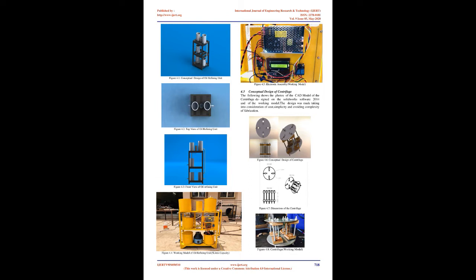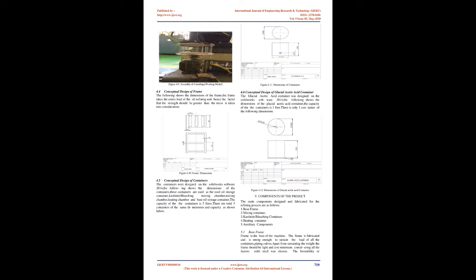Followed by dehydration. 1.4 Dehydration. The used lubricating oil usually contains aromatics and water content etc. Heating at high temperature removes emulsified water and mixed lighter fractions of fuel oils in the heating container. In the dehydration, heating takes place at approximately 110 C, where the entire water content is removed.